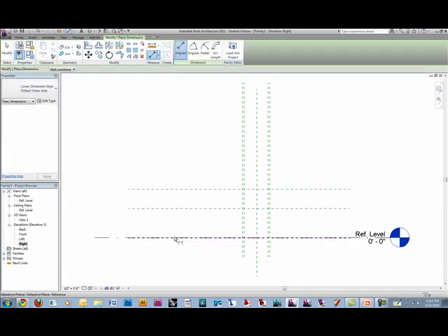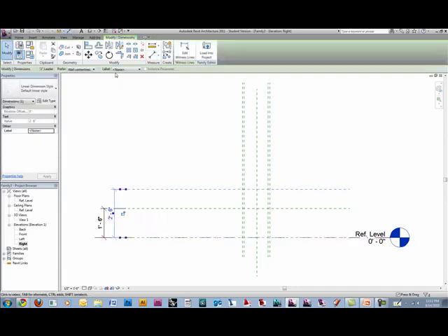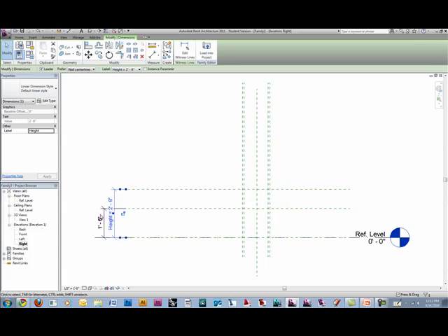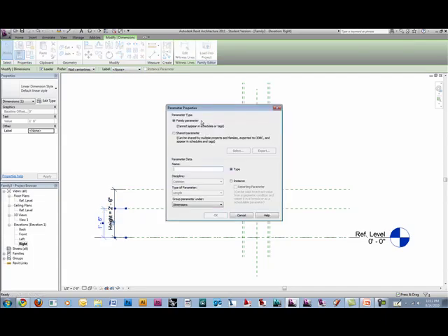We want the plane under it, not the reference level. And you can't do both of them at the same time either. You have to do them separate still. So, ta-da. This one's going to be add parameter height. And this one is going to be seat height.